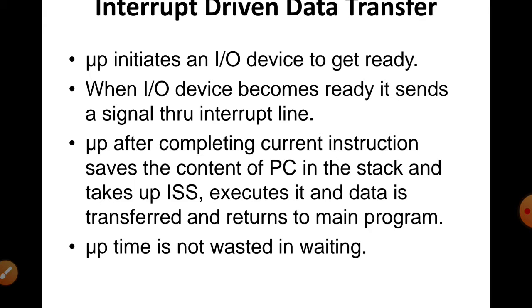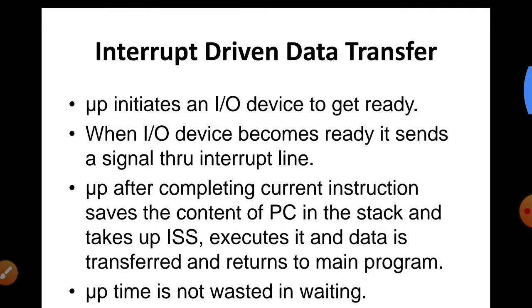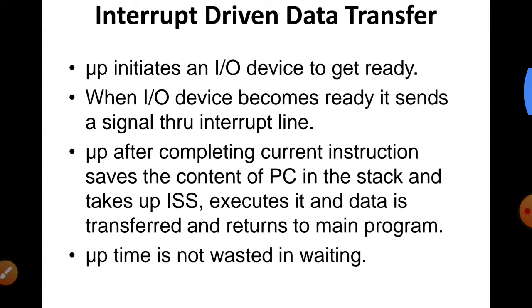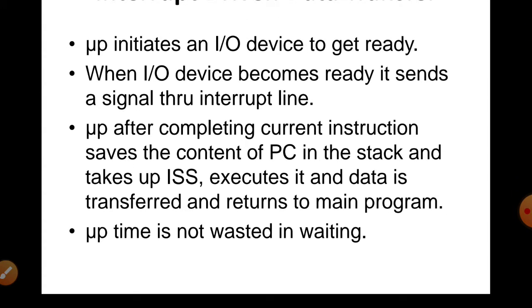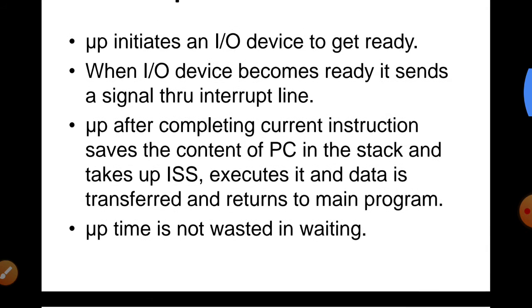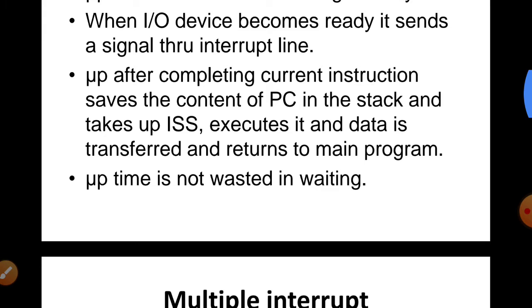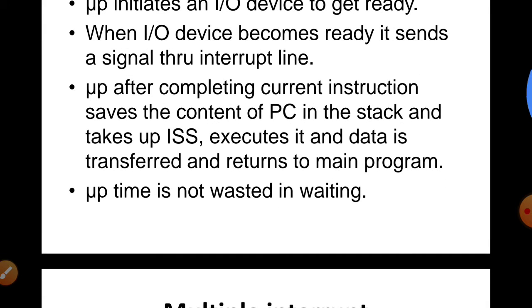Now the microprocessor can ignore or delay the maskable interrupts if it is performing some critical tasks. However, it may respond to the non-maskable interrupts not immediately, but after some time. In many ways, you can take an analogy of a telephone kept off the hook, which is ringing, and whenever you are interested, while doing something, you take the message.